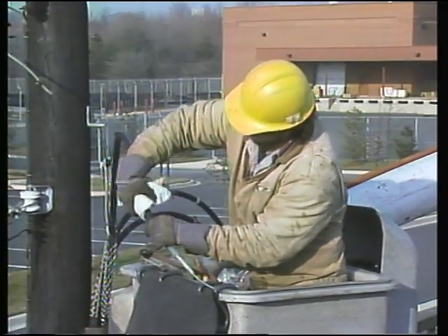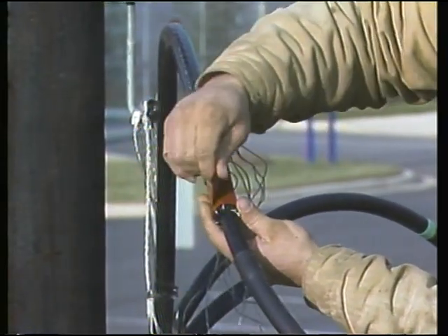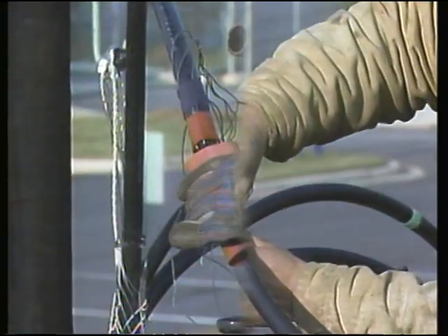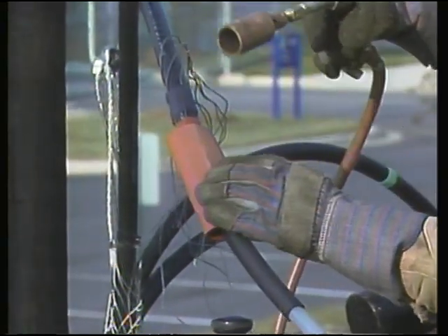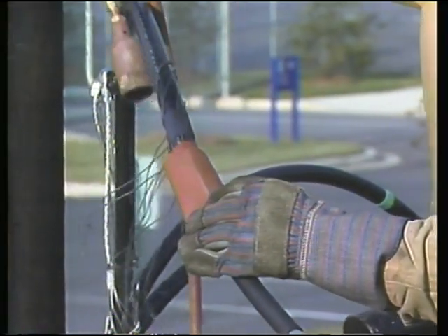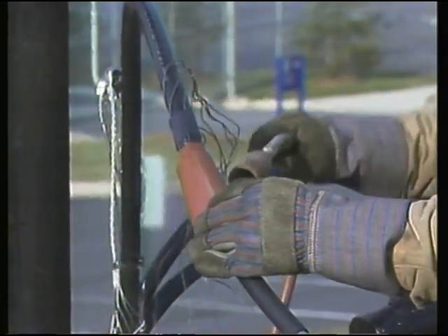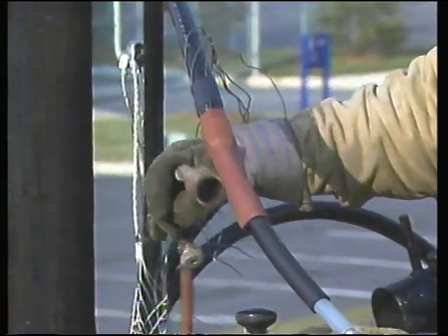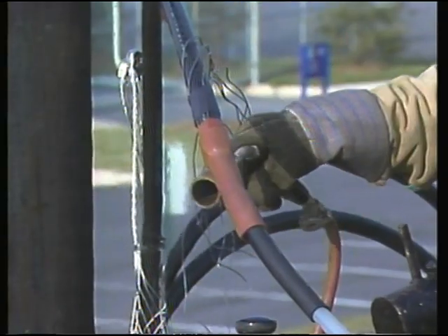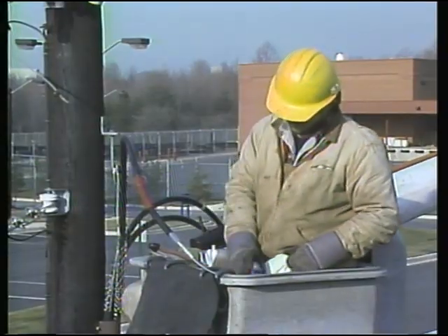After the tube is in place, the workman cleans it using an approved solvent. Then he applies a layer of red sealing putty to the cable's metallic shield. Next, he positions a second heat shrink tube at the edge of the red sealing putty. This tube provides insulation. This tube is also applied using an approved heat source and a brushing motion. The tube is properly applied when it appears smooth and wrinkle-free. Again, after the tube is in place, the workman cleans the cable with an approved solvent.